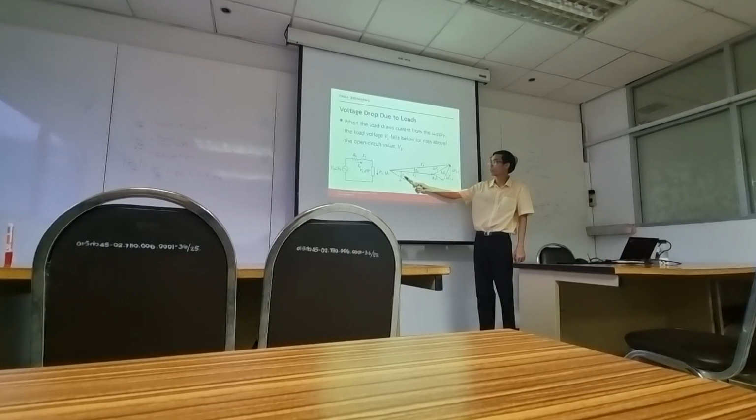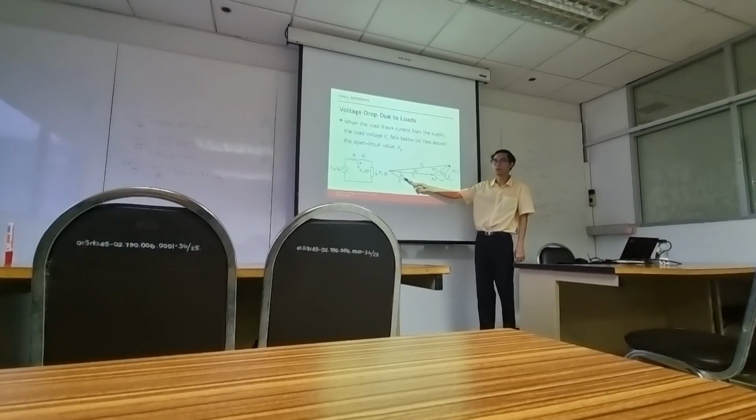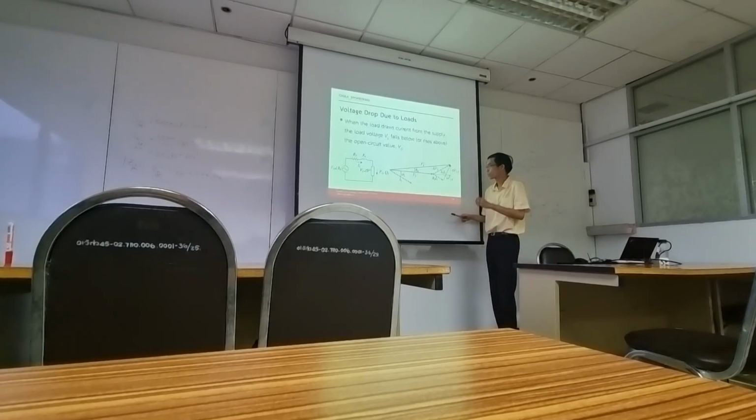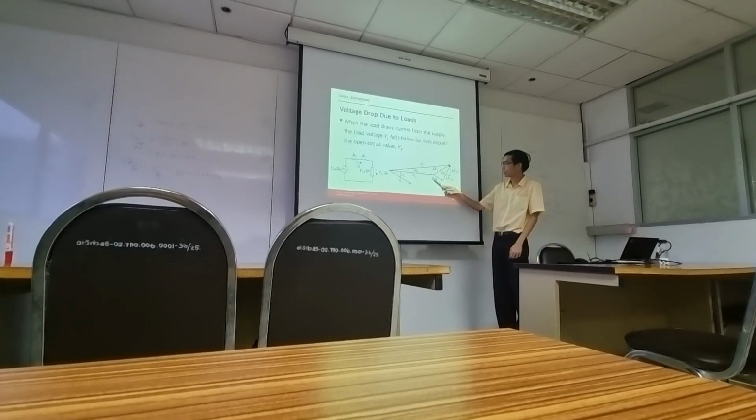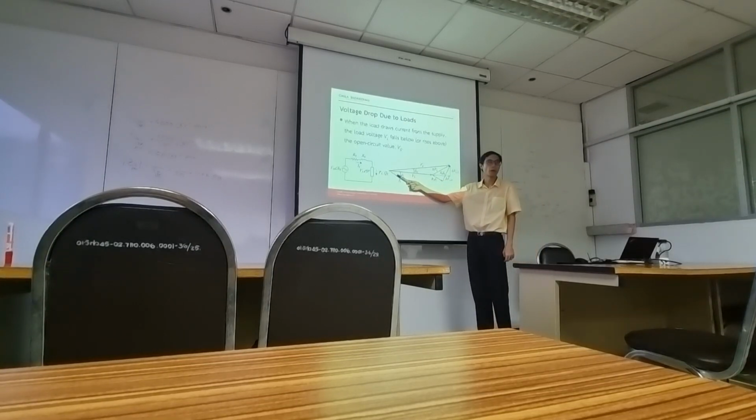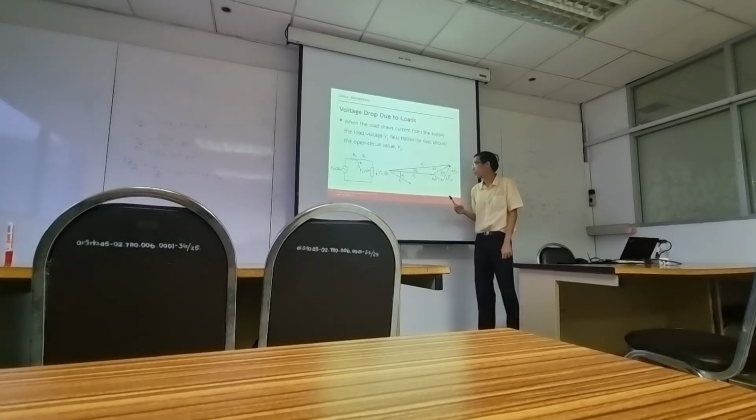And the angle here is theta L. This angle is just the power factor angle. Okay, this is load voltage and this is load current, so this is the power factor angle at the load. RS is a real number, so this and this are parallel.